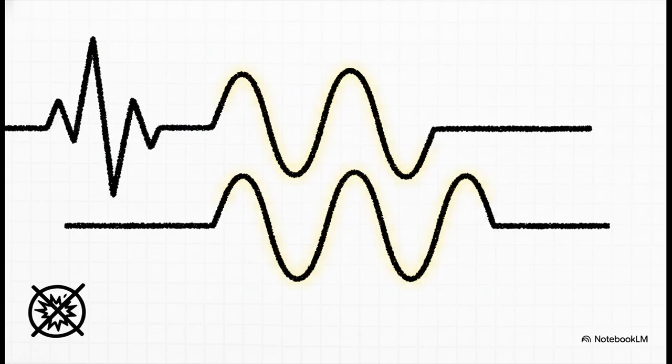You see, the power grid is like a massive, thumping heartbeat. Our synthesized AC waveform must perfectly align with the grid's voltage, its frequency, and its exact phase. A mismatch here? That would cause incredibly destructive circulating currents. In fact, if the grid suddenly loses power, the inverter has to instantly detect this and sever the connection. This critical safety feature is called anti-islanding, and it ensures your solar panels don't accidentally electrocute utility workers who are trying to fix a downed line.